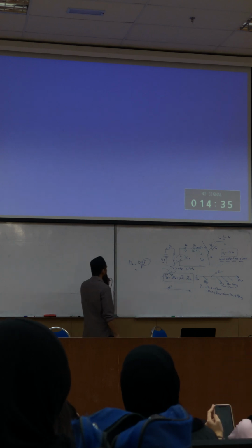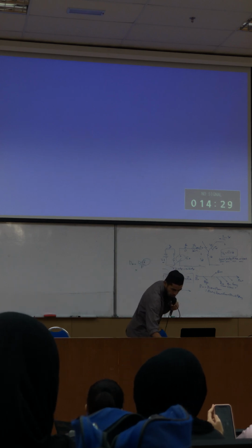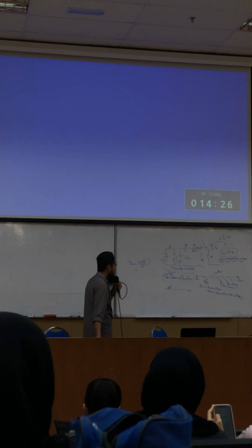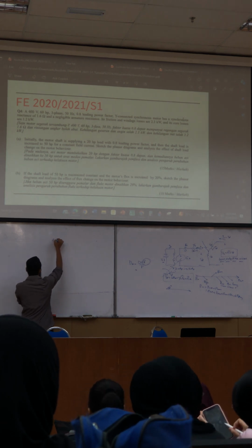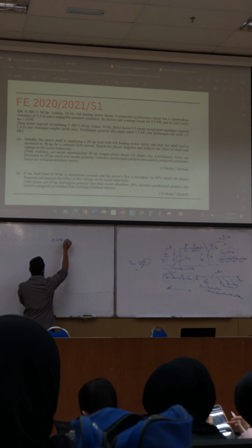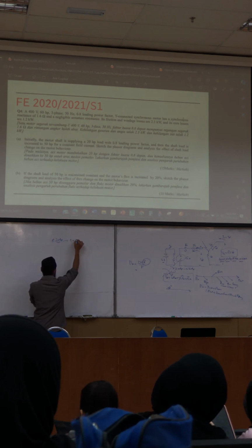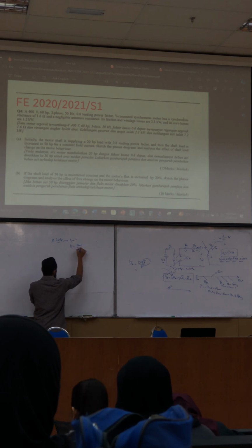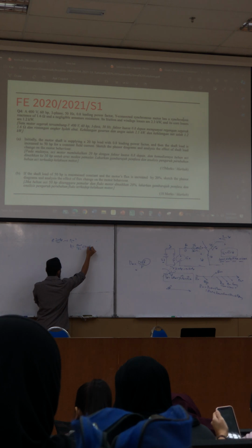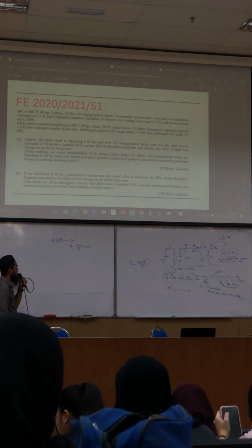So for this moment, we start by finding out the efficiency or the performance of your machine during these two conditions. Start with 20 horsepower, what is the performance there? What is the efficiency at 20 horsepower? Let's find out. So efficiency is equal to P out over P in times 100%.